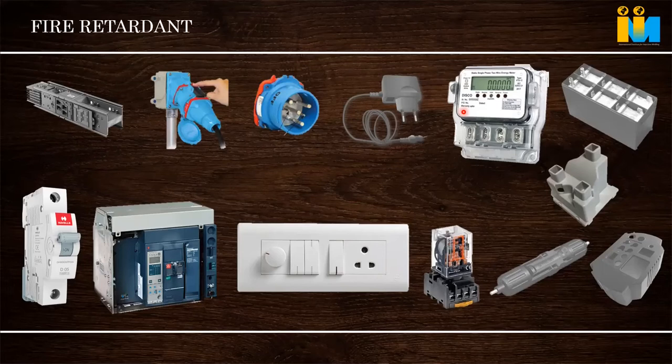But when we go to a transparent material, generally we will not get a material which has a higher flame retardant rating at lower thickness. So I have opaque polycarbonate easily available at 1.5 mm V0, but transparent is very difficult to get. Normally 3 mm V0 will be available in the market. So then we have to design the part as per 3 mm if we want V0 itself. That's how it is done.